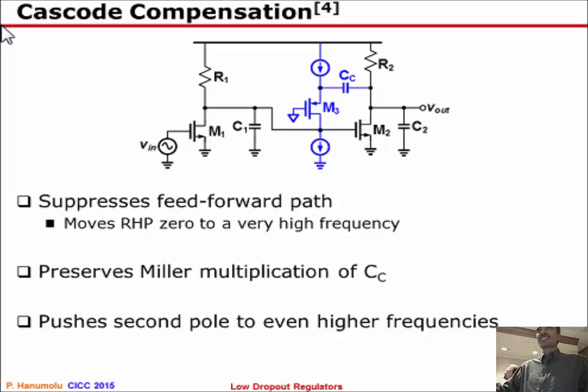But those resistors can be changed rapidly in order to change the output instantaneously when the load current changes from, let's say, 0 to tens of milliamps, would be one way. But if you want to have good rejection, then making the loop faster and faster probably could be one way. Or, yeah, I'll stop there. We can talk later.